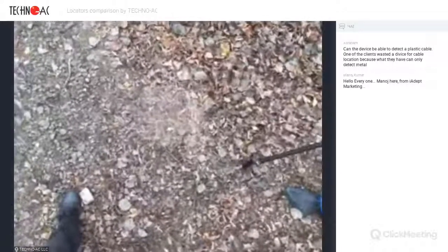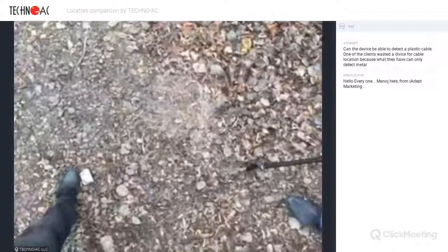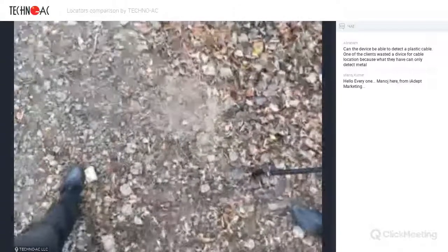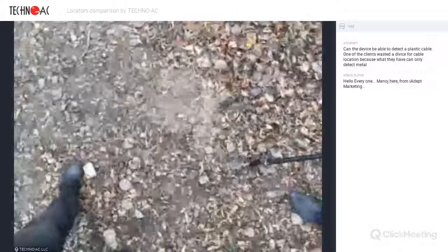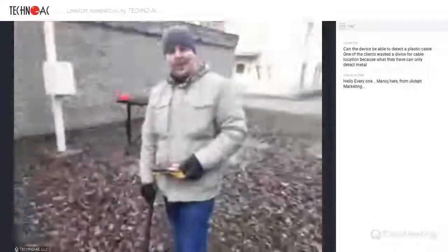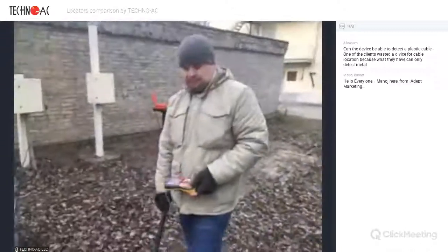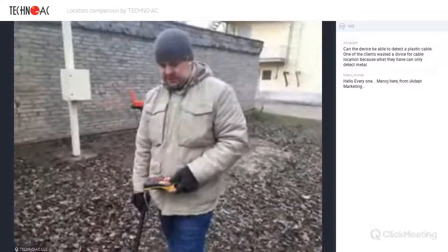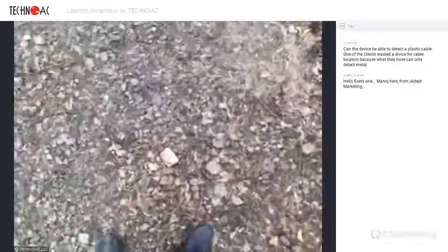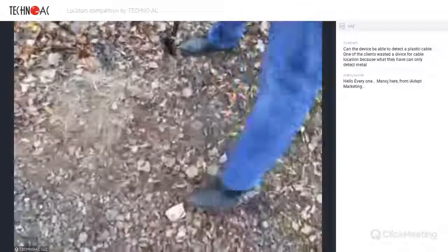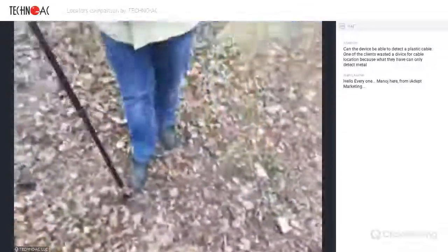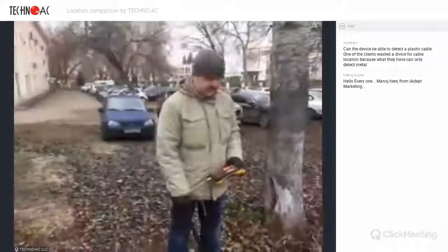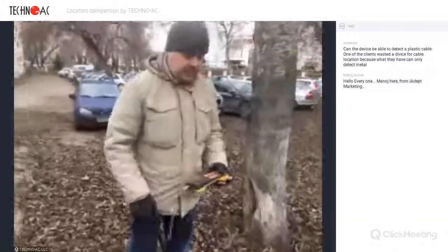this distance between the rock and the sensor head here is equal to the cable depth below the ground surface. We call it the trigonometric way of depth evaluation, but generally it's easy as that. As you remember, we had 60 something centimeters, and now you can evaluate by yourself that this is approximately the same depth here. I guess it's close to true.